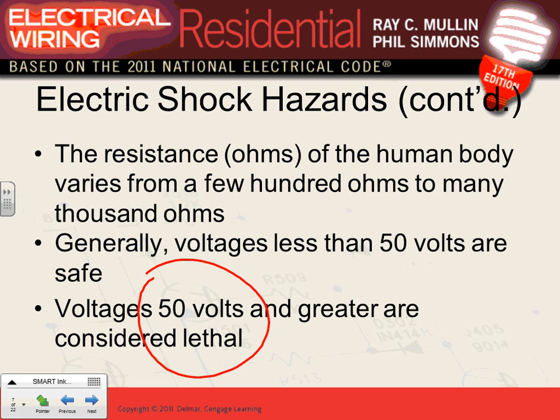That's where the voltage becomes a big deal. You can have a certain amount of amps, and in order to push them, it becomes lethal to push these amps right through you if the voltage goes higher than 50. Does that make sense? Voltage, guys, is the push, the one that pushes the amps. The amps are great. Bigger amps will kill you, but you need somebody to push these amps. It becomes lethal in terms of pushing the amps through your body or through anything else when the voltage goes higher than 50. And this is why we require 50 or more to be a grounded system.